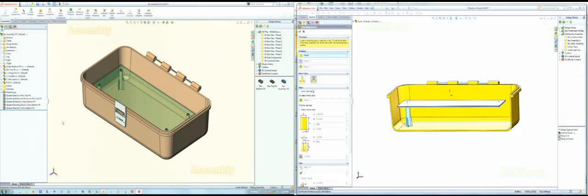It's kind of like when you do a thin extrude. Once you do a thin extrude, you can't turn it back into a regular extrude no matter how you try. The mounting boss seems to work the same way. So you get more choices in the initial feature, and then after you decide on which one you want, now you're stuck with that. Within this feature, you can always delete the whole thing and start over.